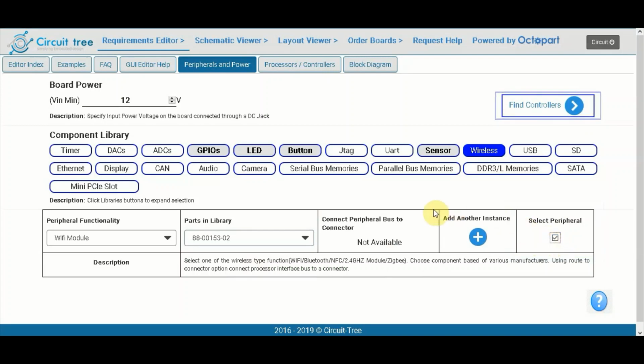For changing the power, change the default 12-volt power to 5-volt here. The power entry method here is a power jack. For USB-powered battery connections, connector-powered, use the advanced menu to change these options.